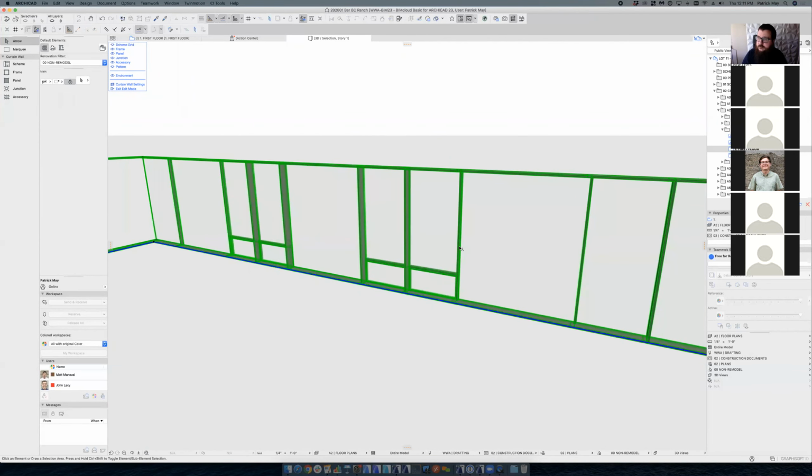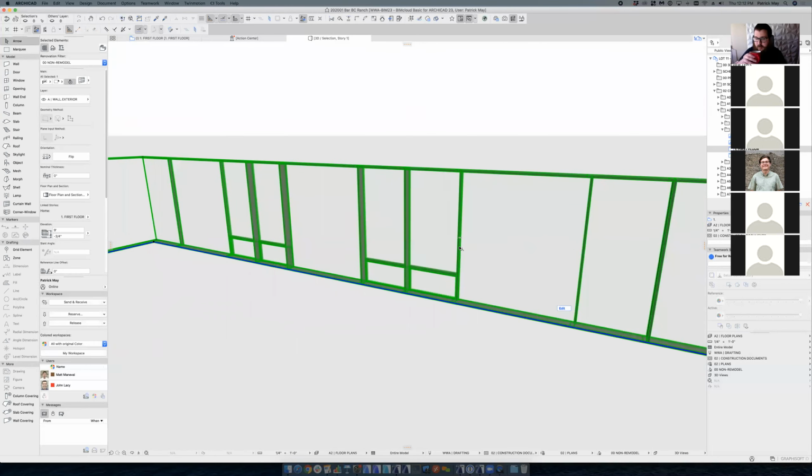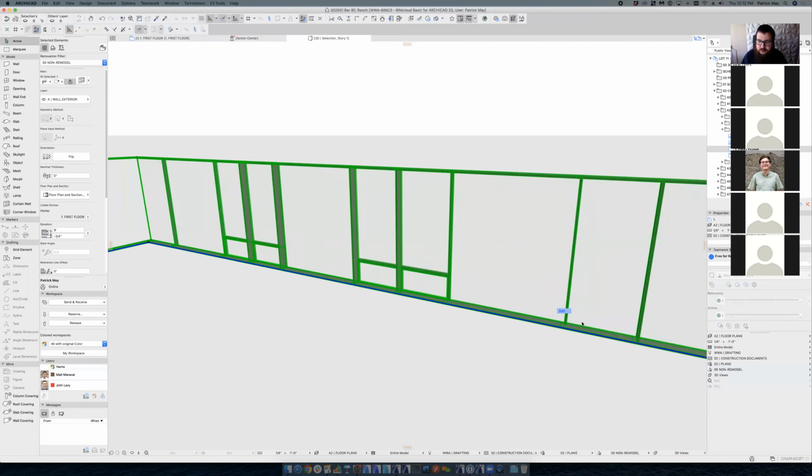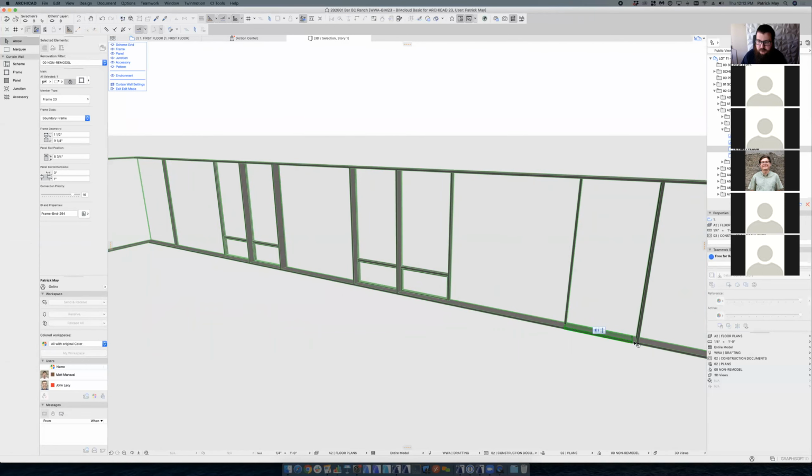And I'll just quickly add that in the curtain wall edit tool that Pat was just in, it's possible you can draw custom frames, custom mullions, you can add custom conditions. You could make that big panel a cased opening without breaking your pattern.